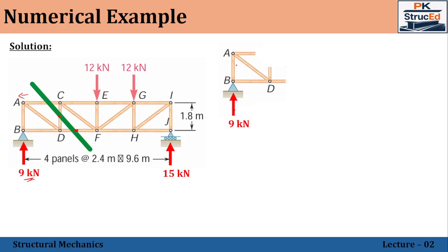Now, introducing the forces in these broken members, that is the internal forces being exposed in those members. Let me assume all the forces are in tension: FAC, FDC and FDF. You can see all are directed away from the joint, that is, we are assuming the members are in tension.